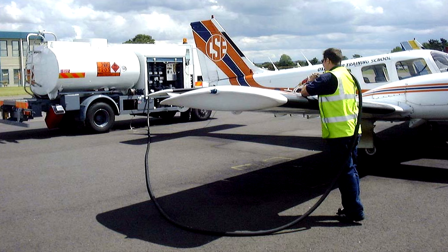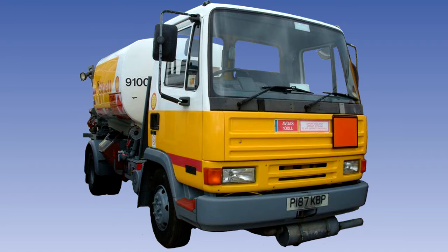Piston-engined aircraft use gasoline fuels grouped under the title Aviation Gasoline or avgas. Aviation gasoline is manufactured to conform with the exacting specifications that are issued in the United Kingdom by the UK Aviation Fuels Committee on behalf of the Defence Material Standardisation Committee. The specification number for gasoline is Defence Standard, or DEFSTAN 91-90.